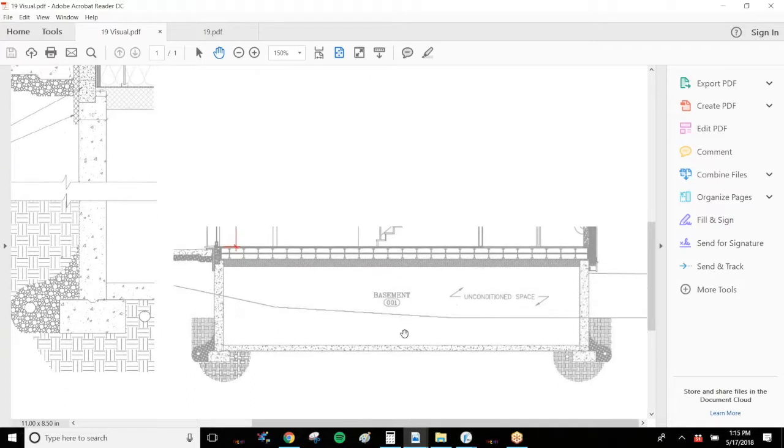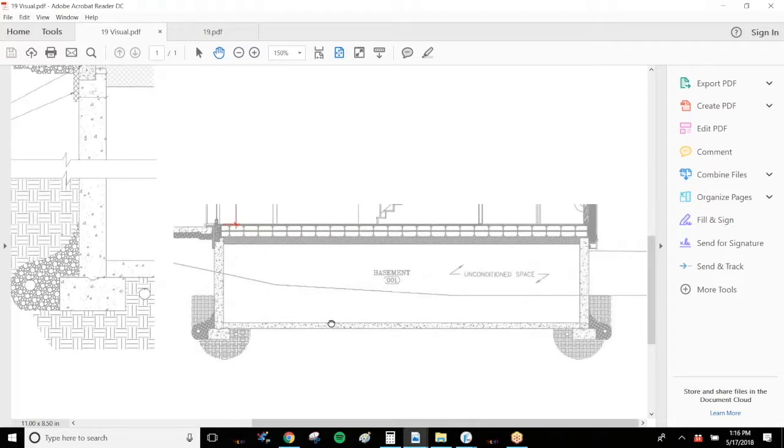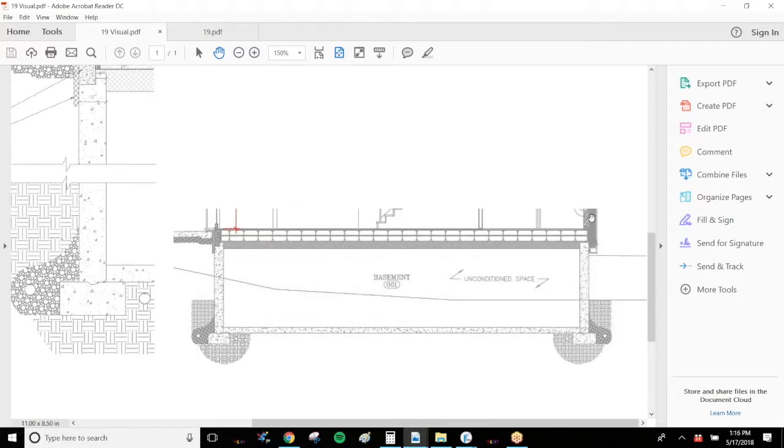You need to look at the whole building section though, so this is just a clip here where there's like a porch. So the entire basement wall is below grade, but it looks like a slope site. So on the right hand over here, it looks like the basement wall is actually exposed. So it's a walkout basement or condition like that.